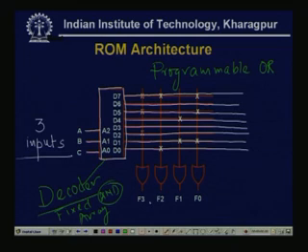So, F3, see here there is a cross point, this is one cross, this is one cross, this is one cross. So, what is my F3? My F3 is this min term coming from D7, that means my A, B, C, say if it is 1 1 1, in that way we take.